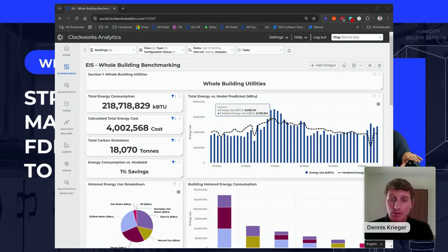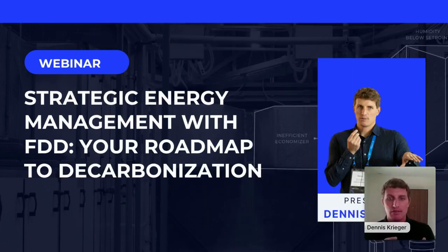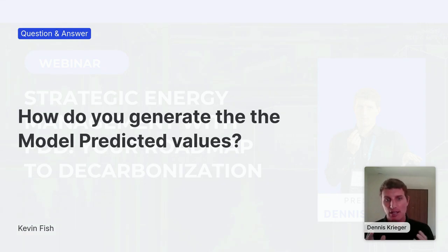For this building, on the typical weather conditions that we just saw, this is where we would have thought you would be at that moment, right? By normalizing that performance and being able to compare to a predictive model, you can get more accurate ways of saying we are actually saving energy. The actual meter itself might be higher because it's hot outside, but given that comparison to other times in the year where it's been hot, we're actually doing better. That's how you can really start to see through all the noise of meters and how they change and evolve over time.